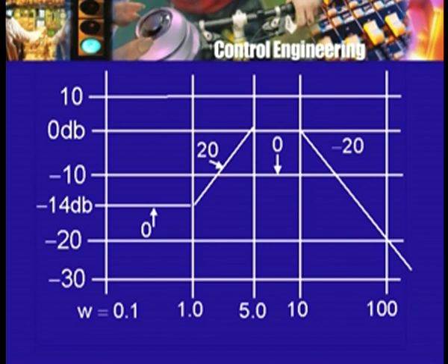So, let us say here is the 10 dB line, then I will have 0 dB, minus 10, minus 20, minus 30. So, here is the 0 dB line, here is the minus 10, minus 20 and minus 30 line. I have to choose the vertical scale appropriately depending on the height and the width of the graph paper that I have. I am not going above 10, I am not going below minus 30. So, this is adequate. So, an appropriate scale has to be chosen.